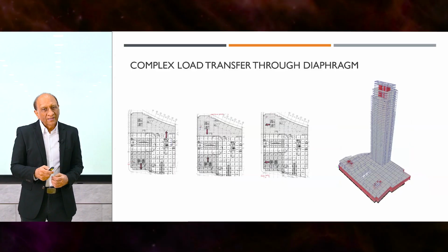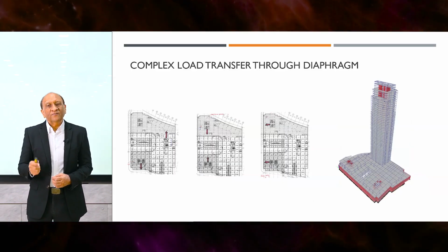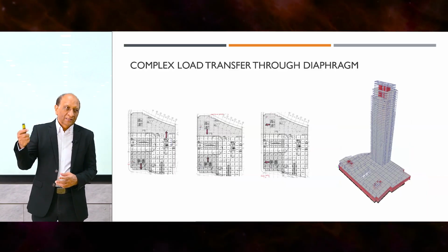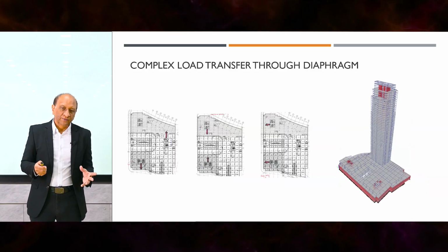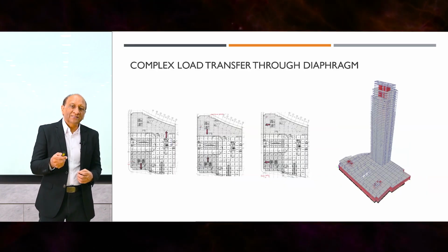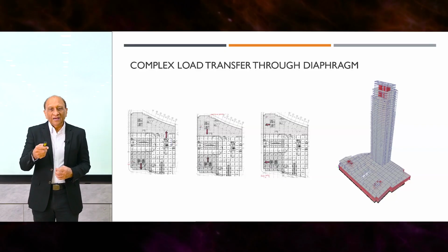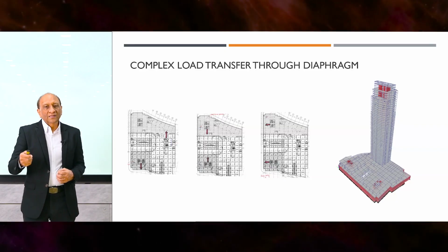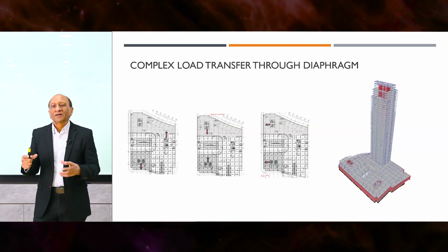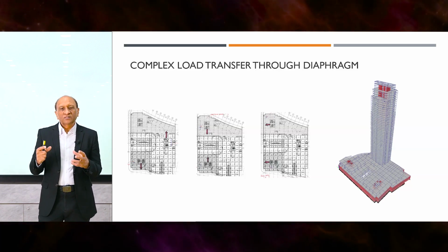And the problem is that these towers will be built at different times. One tower now, another tower in 5 years, then another one. That means the diaphragm is built first, the podium is built first, but the towers aren't there. So during that time, if the earthquake comes, we have different ways that the load can transfer. And the core walls in the podium are already built, but the tower is not built.